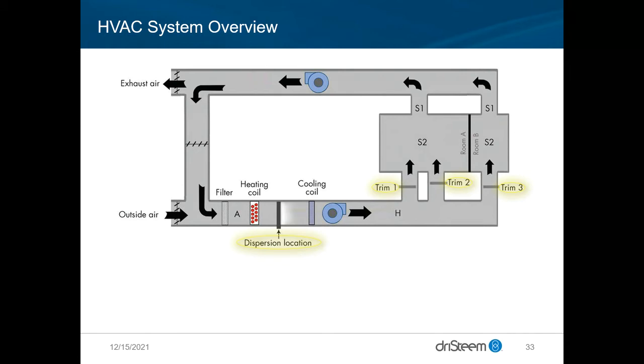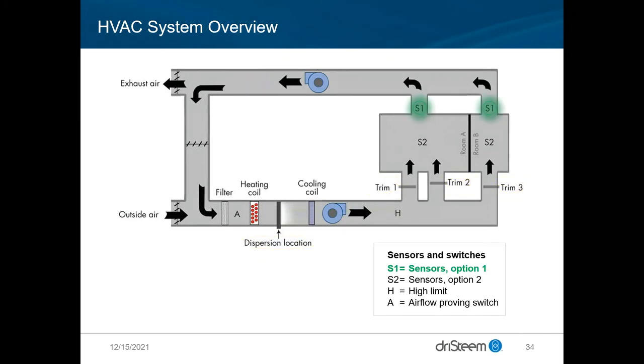This example is showing an overall concept for a building with multiple zones that may be at different levels of humidification. So you can do your base humidification in your air handler, and then put trim humidifiers in the different spaces as needed if they have higher requirements. That gives you the best overall control and variability for the different parts of the building.